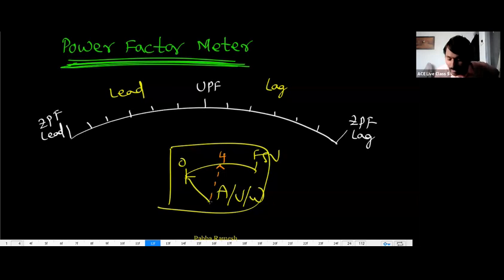That's why we have used the spring type of arrangement. During the operation, the springs will be getting disturbed, meaning force will be developed. If the supply is switched off, the springs will try to go back to their original position. So automatically the pointer has to move back to 0, because in this type of instruments, 0 is called the initial value. That's why springs are used.